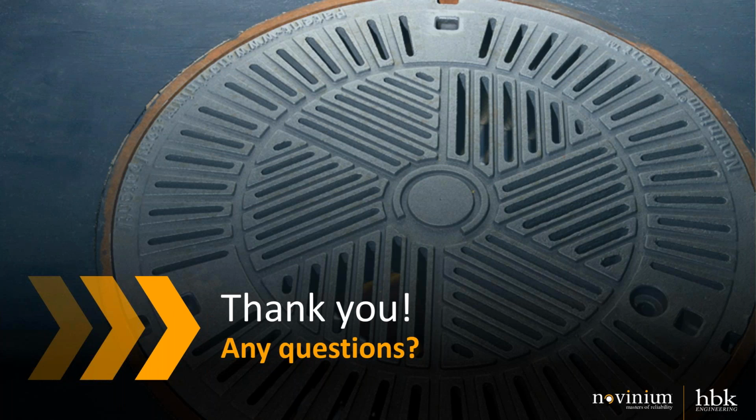I do. I think that generally establishing a baseline, and that first would be the establishment of a criteria of what actually represents deficient in terms of my assets, whether it be electrical or structural or mechanical, but then also going through and creating that baseline. In other words, so when you start monitoring on that, you're monitoring a known quantity as opposed to going into an environment where you've established no control at that point. I think by establishing your baseline data set and then monitoring, you have your starting point, and then you start to watch for your variations from that baseline, which at that point puts more meaning into the information you're receiving back.